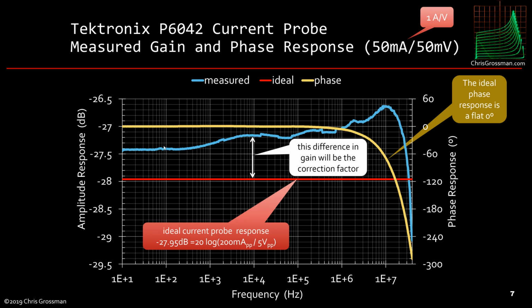So now if we look at this magnitude plot, we see little jumps in the magnitude plot here. The biggest one is perhaps this one here. What these are from is the way that the Bode plot function in the scope works. It does its best to match the size of two waveforms by adjusting the coarse and fine attenuators of each of the inputs of the scope. Now the attenuators are not perfect. There is error in each one.